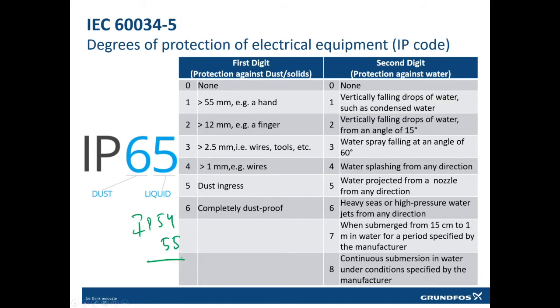These are the standard surface motors we use as per IEC standards, and these motors are good for pump rooms and will work most of the time. They are dust proof and withstand water splashing from any direction or water from a nozzle. But it is not advisable to throw these motors inside water or a swimming pool. It will not work after.